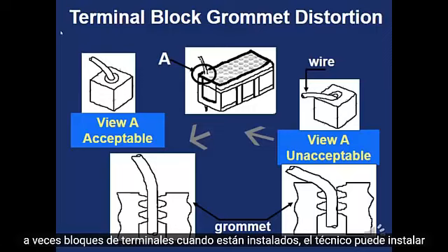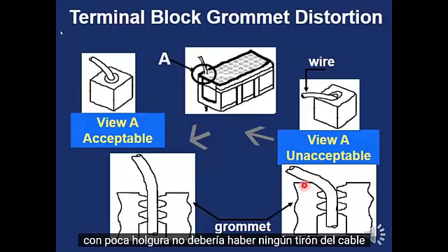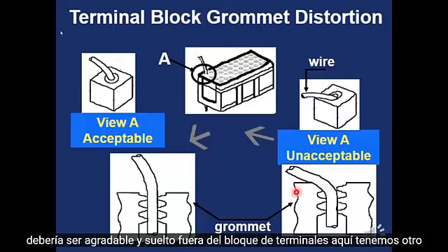Sometimes with terminal blocks, when they're installed, the technician might install them with not enough slack. There should not be any tugging of the wire. The wire should be nice and loose outside of the terminal block.